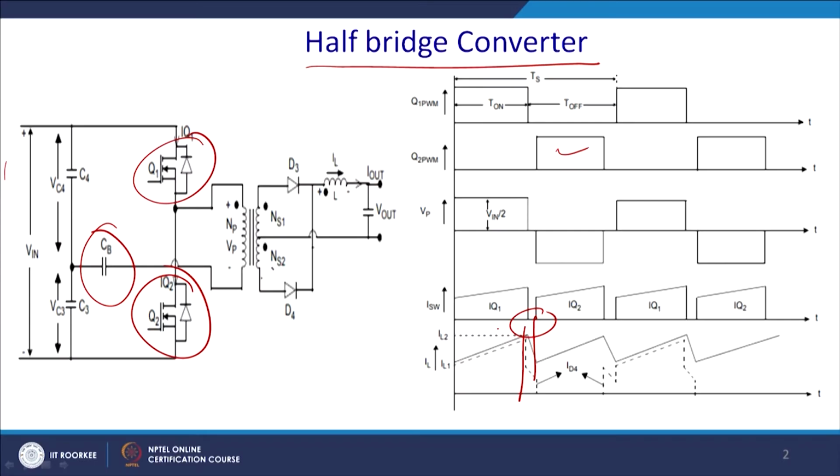So, this is the time where the diode conducts, and also in this case you can see that diodes D3 and D4 conduct depending on different criteria, and this is the current to the inductor, and we will have a ripple, which will be suppressed by this capacitor.